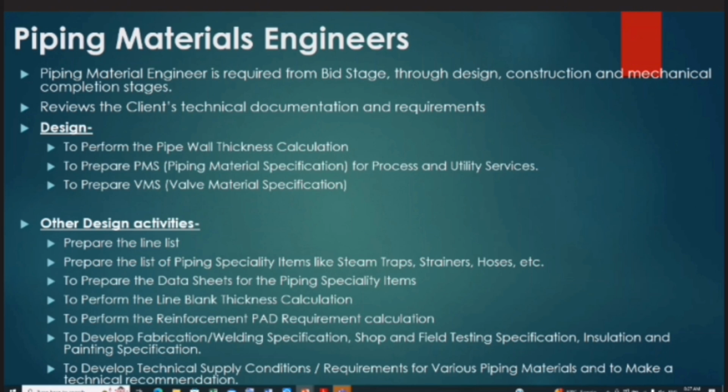Then we will go to the different vendors and tell them we want this component. For example, we want 10,000 kilometers of pipe. We will tell them we want this size and this much length. But actually this is not sufficient. In addition to quantity, we also have to tell them the exact specification. Other than materials, what different testing needs to be carried out? There are so many different requirements, and these are mentioned in different documents, which are generally called the enclosure. For each component, for the pipe, we create a different enclosure.